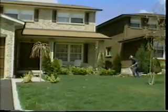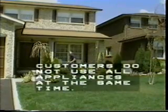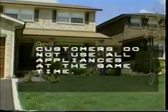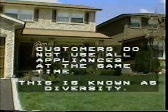However, transformers are never sized this way, since we would wind up wasting a lot of capacity. The transformers would be working at something less than 50% capacity for most of the time. In sizing a transformer, a utility can take advantage of the fact that the customers do not use all of their appliances at the same time. Moreover, the several customers being supplied quite frequently work on a different daily routine, so they tend to balance out each other's demand. This variation in usage of electricity is known as diversity.